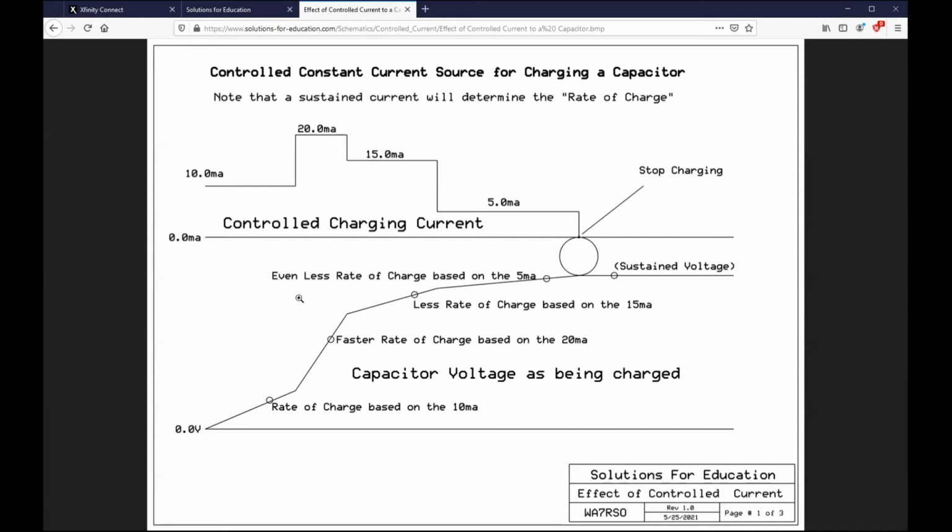And this thing would not work right. And I went, what is going on? And I got this sneaky suspicion that I had way too much ripple in the power supply. So I put a scope on it, and come to find out, brand new capacitors in that disk drive unit had never been formed from the factory. I was rather upset, but I knew what was to be done. So I did what you're talking about. I took the time to hook up a very slow process to build these things up until finally they're up to what they should have been, and then everything worked fine. But had I not known about the forming process, I wouldn't have known what to do.